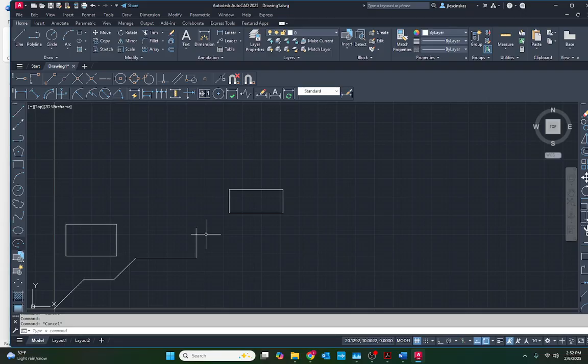If you remember, when I created this line, I created 2 sections. So we only selected the last section because that was the only section that was completely in the box. So if I do this, I'll get those 2 sections, and you can see they're highlighted here. If I right click and then do this, you'll only get the 1 section because we haven't included all of that horizontal section. So that's how the blue or right select window works.